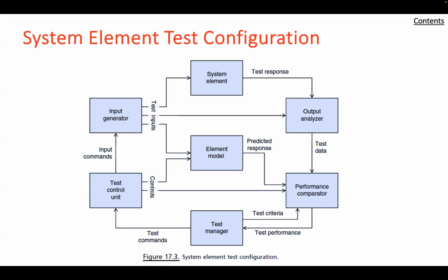One factor that makes the task somewhat simpler is that the environment in which the test equipment operates is usually benign, whereas the system operating environment is often severe. On the other hand, the precision of the test equipment must be greater than that of the system element to ensure that it does not contribute significantly to measured deviations from the specified test performance.